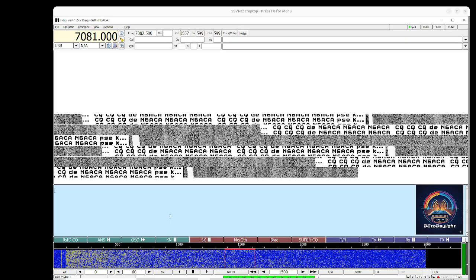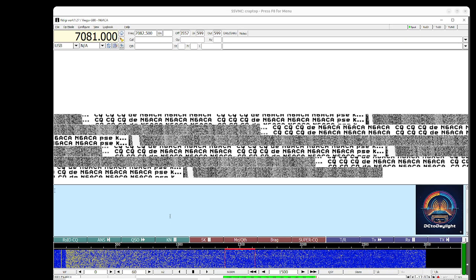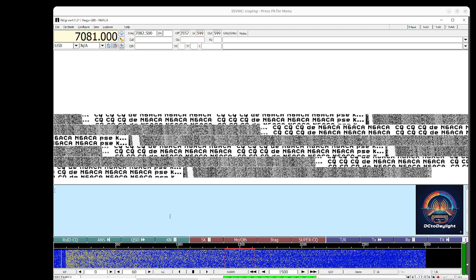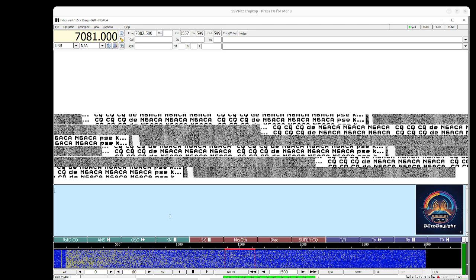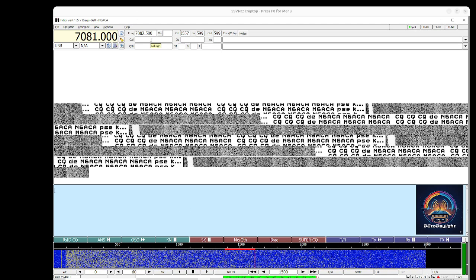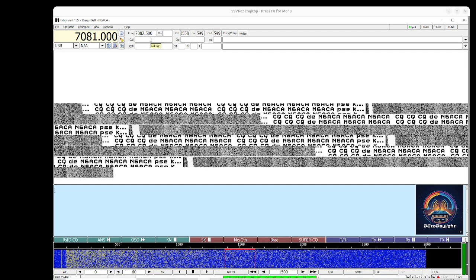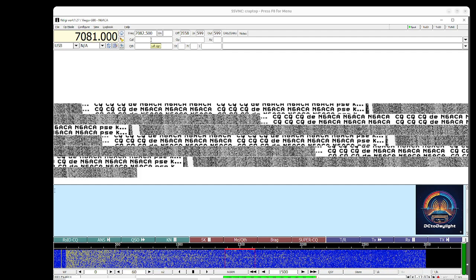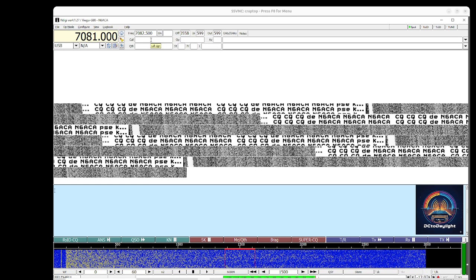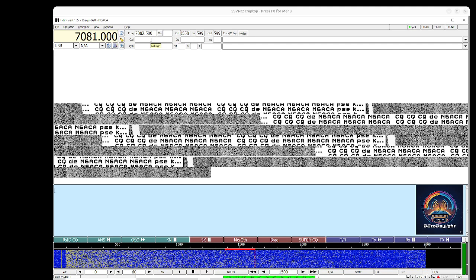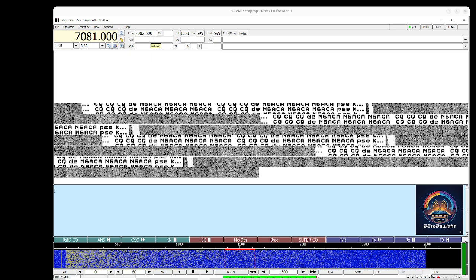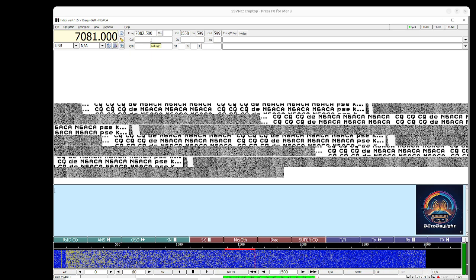If we were to have takers, it would be very similar to how you would have a QSO with RTTY or PSK31. You can't click on the call since it's just an image, so you'd basically go to the call area up here and type in the remote call, and then you'd follow the QSO pattern. Since I'm calling CQ, someone else would use the answer mode, and then I would go to the QSO mode with their call sign, and then we would complete that